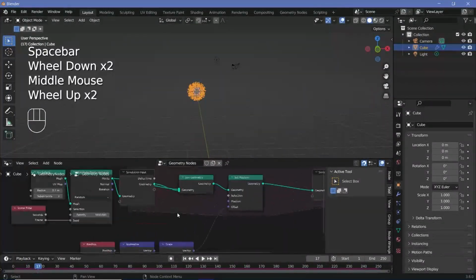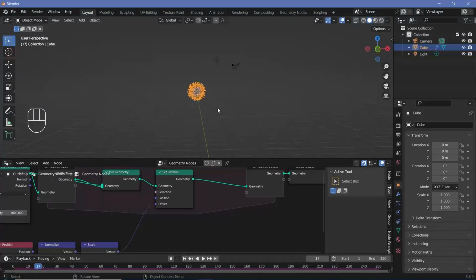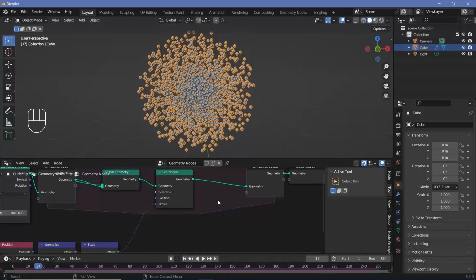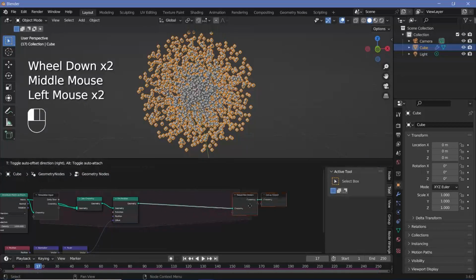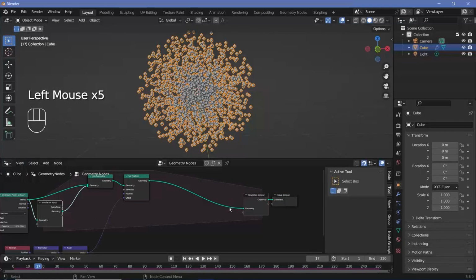So that's going to be really hard on our laptop. So we want to delete particles after a specific number of frames that they have existed. For that we need to calculate each particle's age. To calculate their age, we can create a new attribute, which is going to be fairly simple, and it's going to be similar to how we created a velocity in other simulation node tutorials.